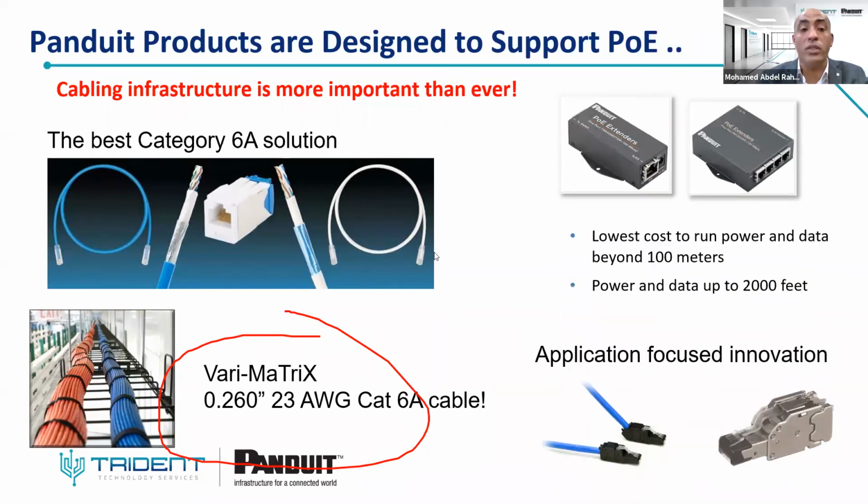And also you can use 28 AWG patch cords when you are talking about MPTL. And finally, we have the lowest cost to run power and data beyond 100 meters by using the PoE extender. You can have a distance between the transmitter and the receiver of up to 610 meters or 2000 feet.